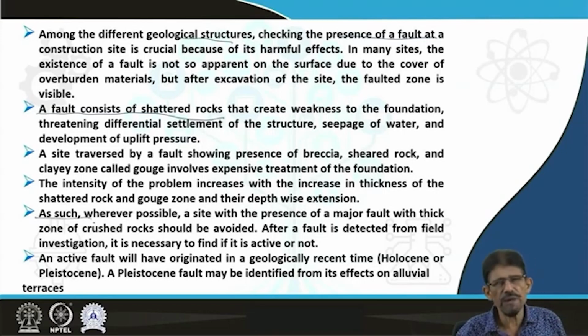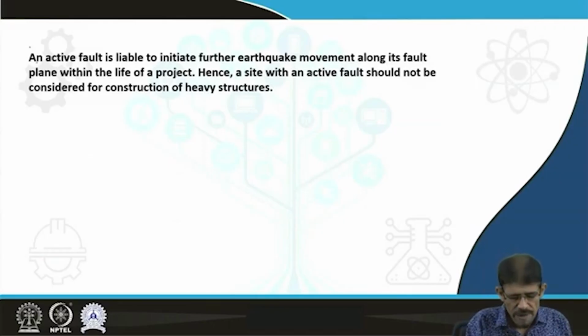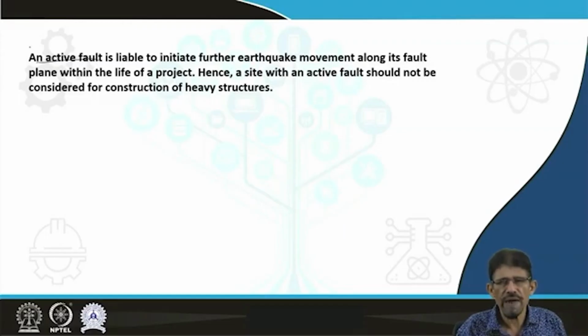Besides this, the presence of a shear zone is a very critical problem in stability aspects of a dam or any structure, because the shear zone consists of deformed, complicated, fragile rocks and requires careful treatment and preparation, costly treatment like dental treatment and others, for minimizing the problem. Active faults are very problematic due to the lot of effect or impact on the nearby rocks, continuous crushing, powdering and deforming the rock associated with the active faults.